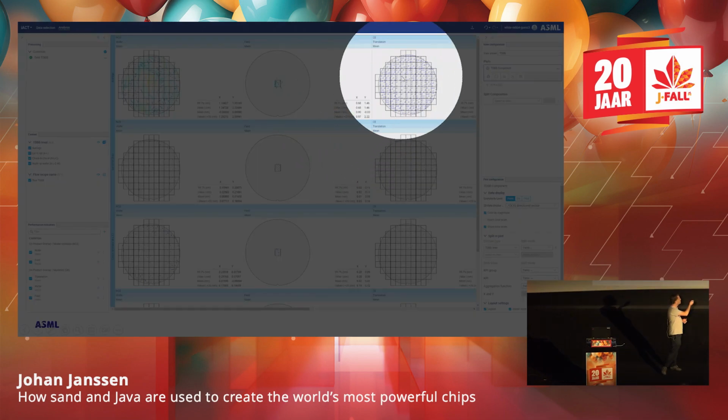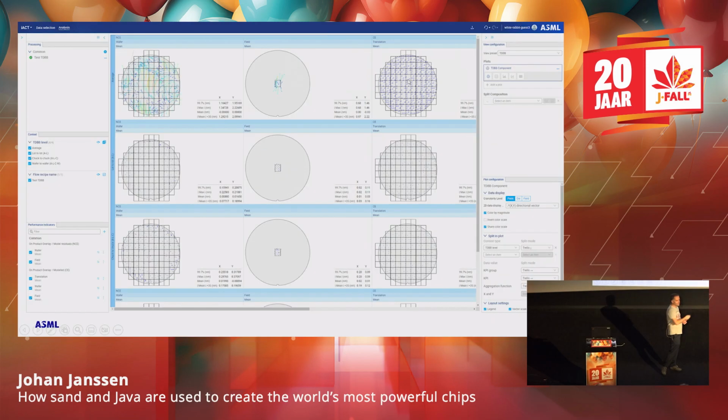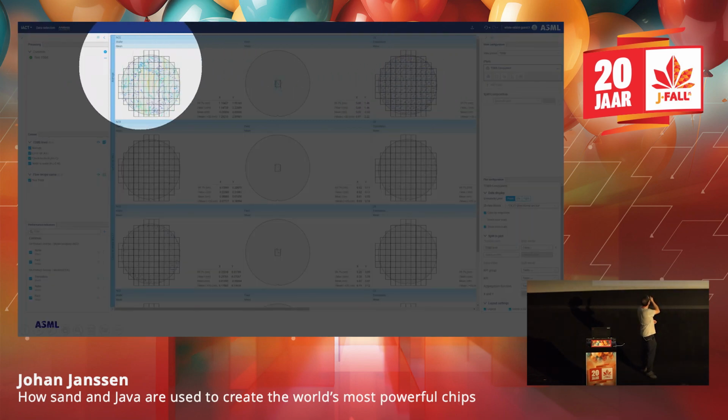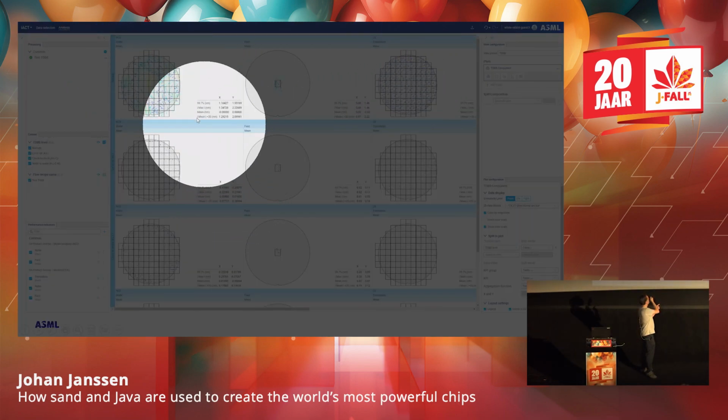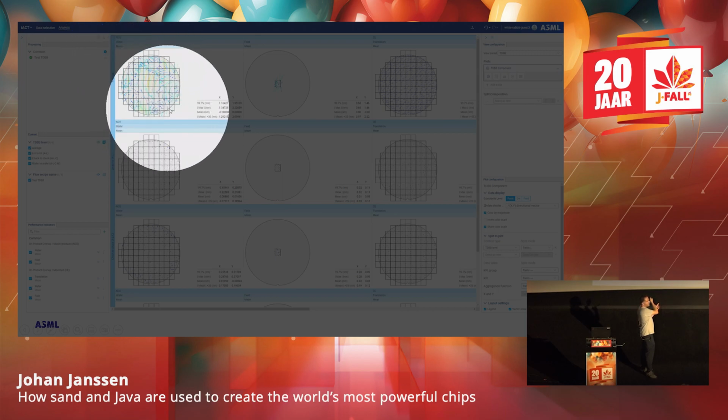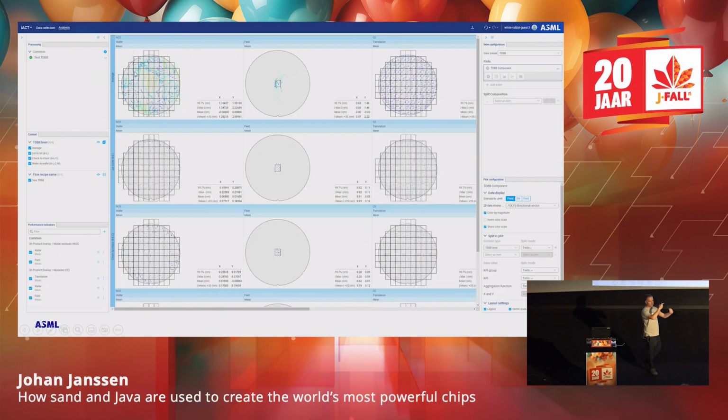If you look at the top left, we see all the arrows pointing in the same direction, like this. If we now recalibrate the machine to print a little bit like this, it's fixed. So that's correctable errors. On the left side, we see non-correctable errors. If you look at the length of the lines and the color, that's basically how bad it is. But this is pointing in all directions. If you have an arrow like this, an arrow like this, you cannot really accommodate that. But if you have more advanced algorithms, you might actually find some correctable errors in this plot.